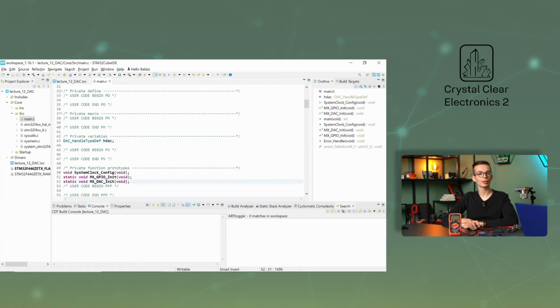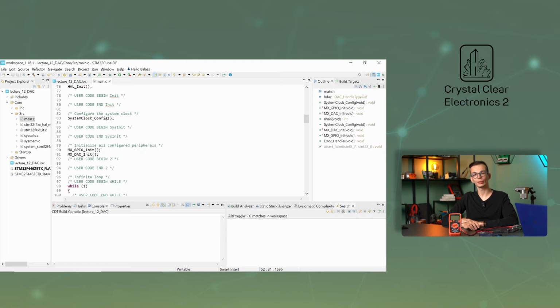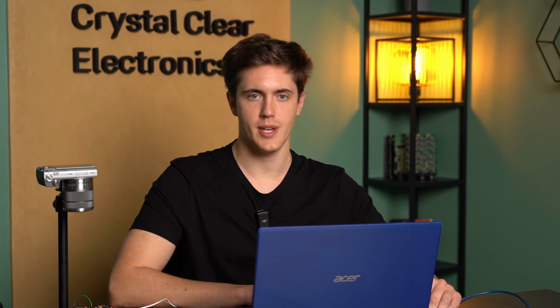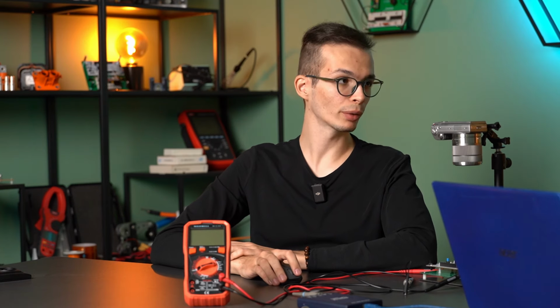The settings are written to the control register by the MX_DAC_Init initialization function. In the simplest implementation, we are only a few lines of code away from our first successful digital to analog conversion. Let's find the USER CODE BEGIN 2 line in the main function. The meaning of this line is that this is where the user code starts. And it is important to write your own code after it, because if you change the .ioc file and rebuild the code according to the new settings, the development environment will delete the code fragments in the non-user code area. Indeed, this is very important.